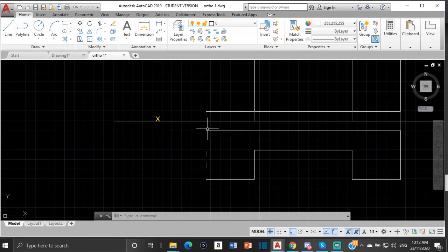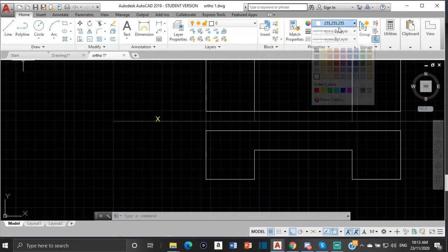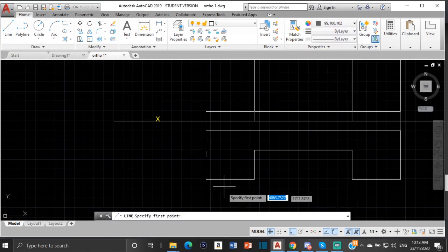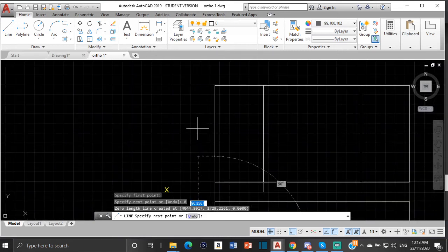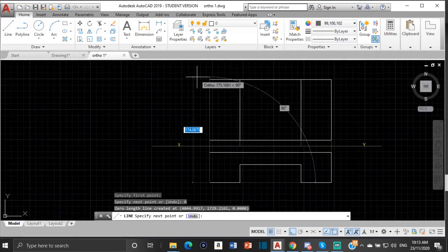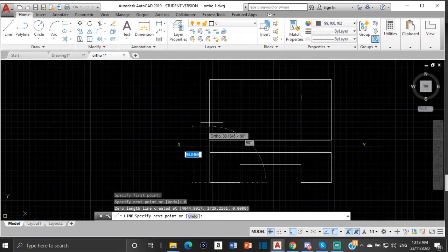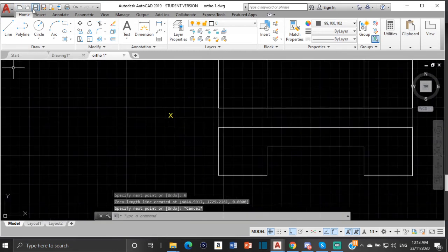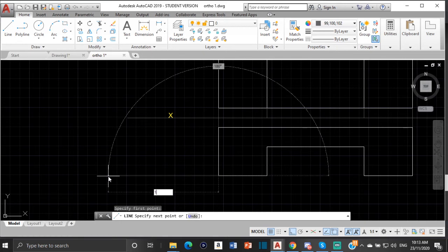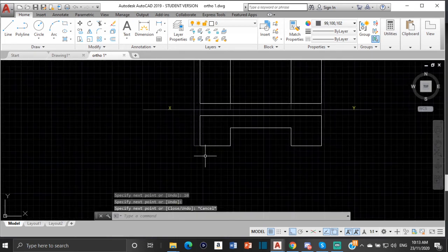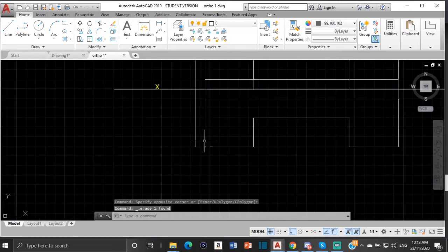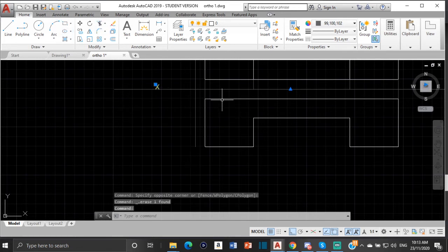To find exactly where that point would be, since we have our XY line here, from here to here is 10, then you have to draw a next line over here that we will call X1, Y1, and that is going to be the same 10 millimeters across over here. So let me just select a construction line, bring this over by 10, and then bring that up. Right now, no specific distance, I'm just bringing this up. Wait, was that not offset by 10? Okay, let me just do this again. Here we go, so that's my point there. And then I bring that up. Good, lovely.